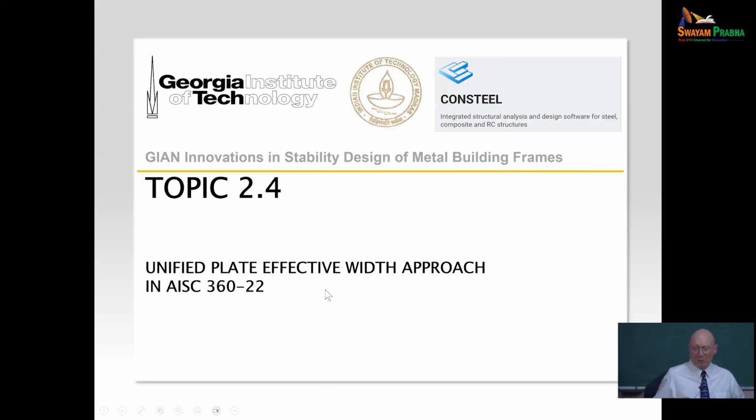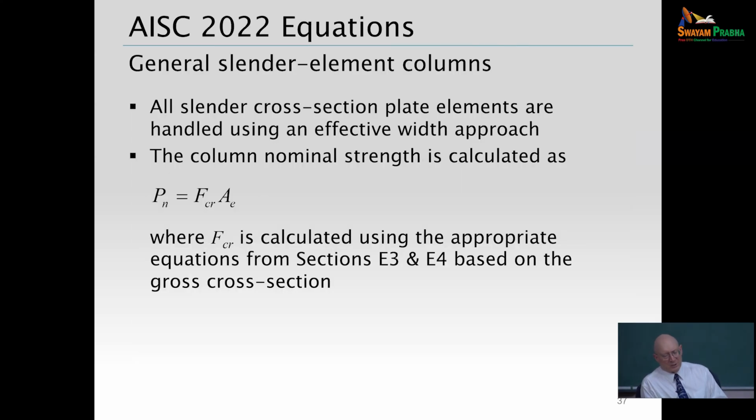All right, so what I'd like to do is to wrap up today with basically a discussion of things that actually came from Dr. Teemu Pekoz at Cornell, and Dr. Kalyanaraman was very involved with much of this work during his research. The unified plate effective width approach. And so this is an approach where we use effective widths for all elements of the cross section.